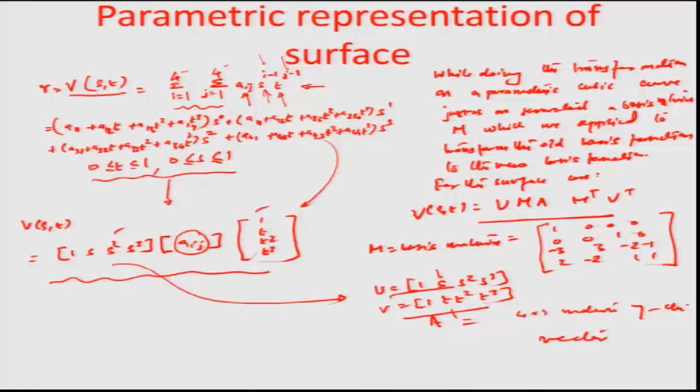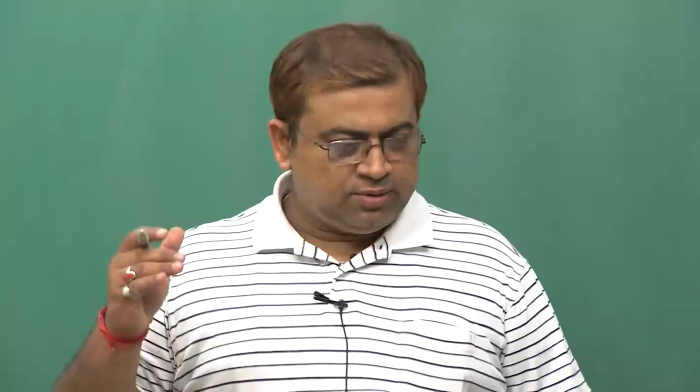So, this is how the data structure would then be created for a surface, because now we send in the various values of the s's and t's in terms of fractions. For example, remember when we were plotting the Hermitian curve, we talked about the various values of t starting from 0, 1/4, half, 3/4, 1, and so on. So we do the same for t and the same for s, and so there are at least 25 different combinations of these values across which you could find an array of points. If I plotted this array of points in 3D space, that is what we are recording as the surface patch. And remember that if there are such patches in series with each other, that would help us describe the surface in totality.